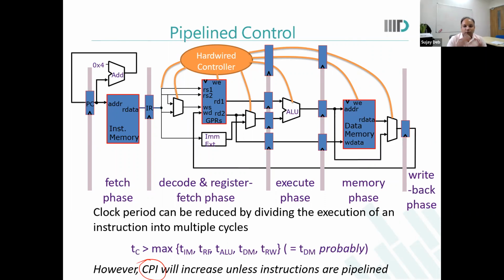For example, inside the ALU you will see that it has a multiplier, a shifter, a comparator, different modules. Now, for a particular instruction, which module is to be used has to be told to the ALU through control signals. If the opcode says add, you tell the ALU to enable the adder unit inside it, and accordingly it will generate the result.